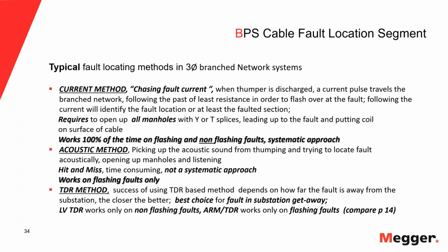But I would say this, from what I have seen: on average, you save time doing it. There might be times you get really lucky and you can hear a fault with a second method that I call the acoustic method. You can, I will not deny that. But many times I have seen the opposite, where you cannot pick a good acoustic signal up and you are just scrambling and cannot make ends meet. So this method to chase the fault current is a systematic approach that will get you to the fault.